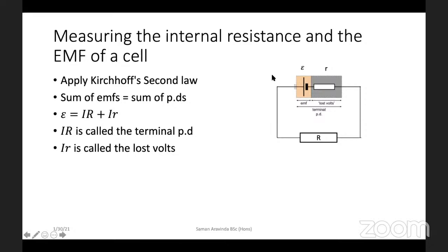So simple r is the internal resistance. It's nothing but another resistance connected in series with this, isn't it? Now just imagine the internal resistance is huge. What can you say about the potential difference across it? It is going to be very high. So is the battery going to be useful then? No, that's what happens when the battery is old, aging. The internal resistance becomes bigger and bigger, so that the terminal potential difference becomes lower and lower.